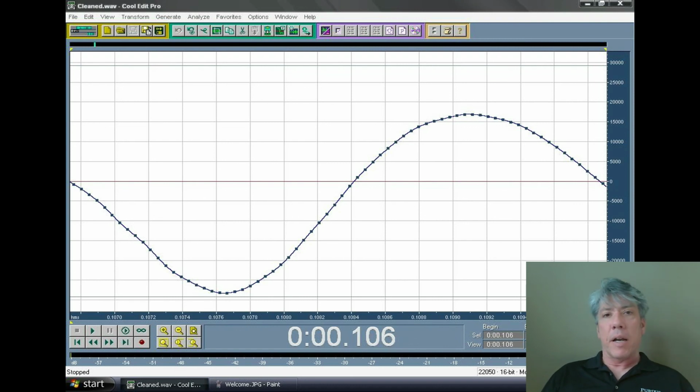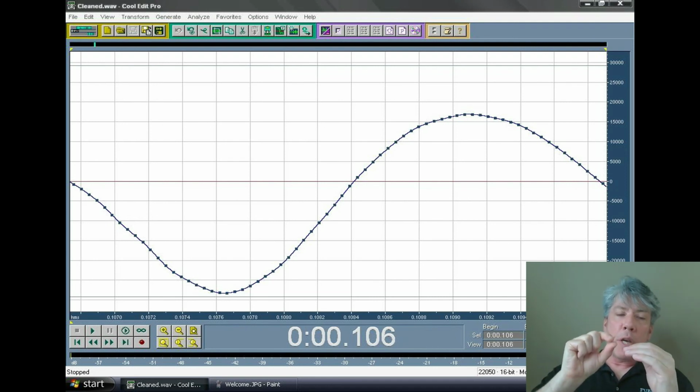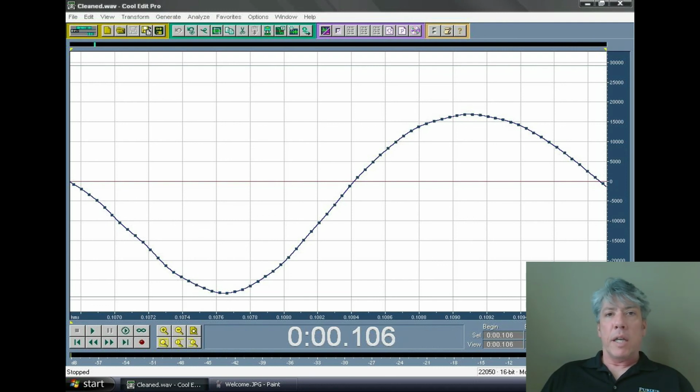You might want to grab a calculator and see what resolution it would be. It's pretty simple. Say you've got a 10-foot tank and 65536 different positions. Just take the 10 feet and divide it by 65536. That's how much change in feet the tank would have to experience in its liquid level in order for the number coming into the PLC to change. It's pretty small. So this would not be bad resolution for the sensor, for level in a tank.